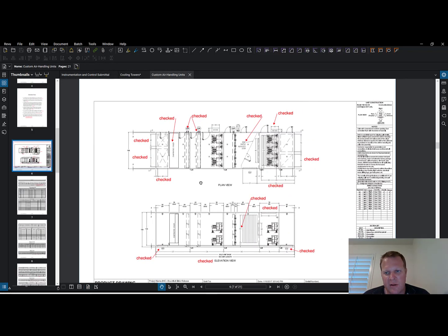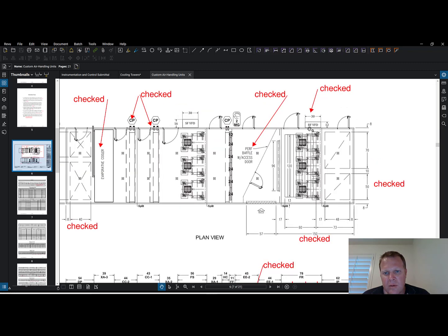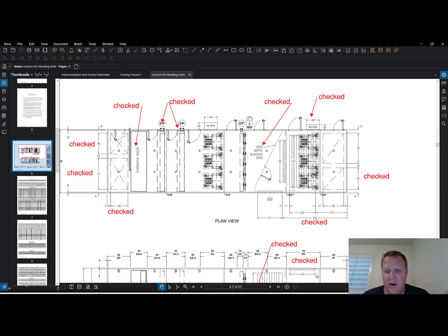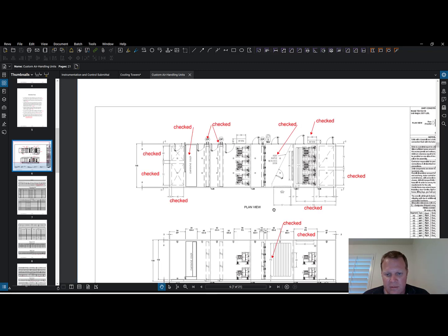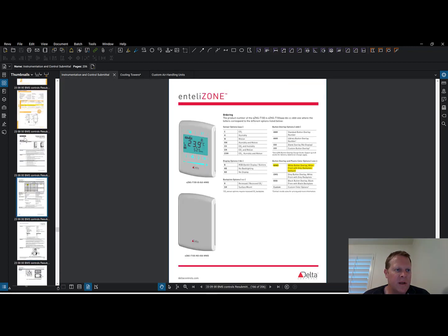Okay, this is the big air handler that's on the roof. And from a plan view, meaning from the top section, we've got the evaporative cooling section. We've got motors for the blower. We've got coils right here. Looks like RF VFDs. So is that relief or supply, return fans? They are in the same unit. Interesting. Okay, let me go find that big diagram.